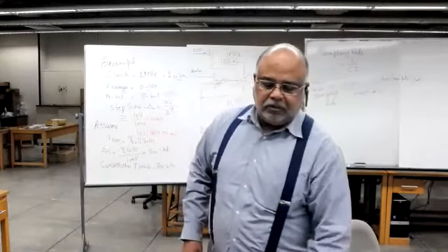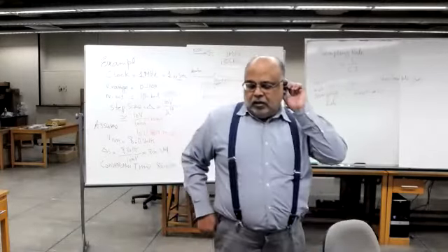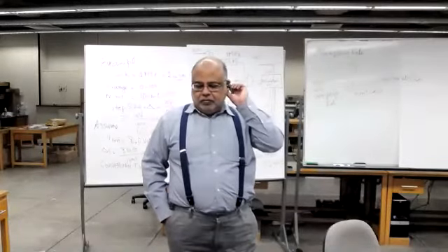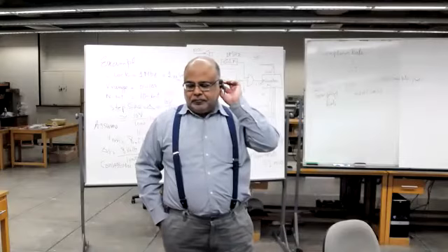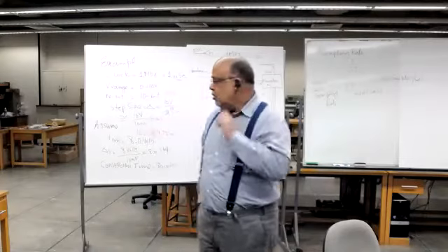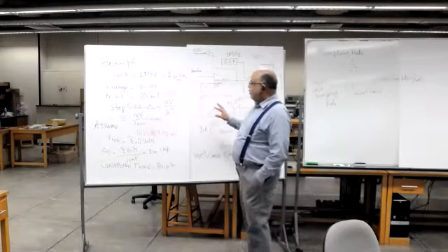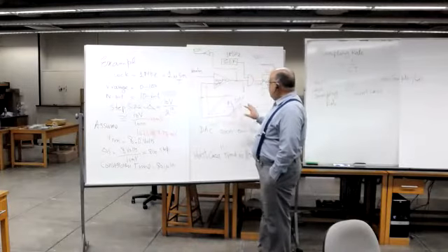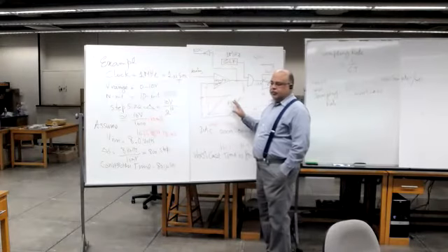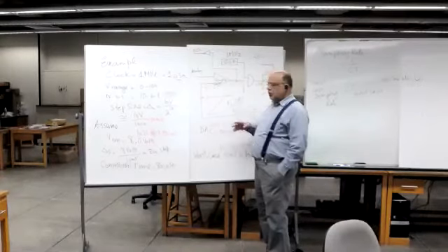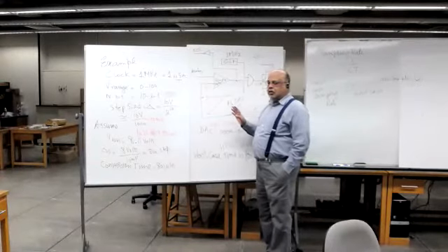And that is very much liked by computers, because computers like things that take a fixed amount of time. So n steps. If it is a 10-bit ADC, for a binary search ADC, it will take n steps. So 10-bit means 10 microseconds. So every sampling will be done in 10 microseconds.